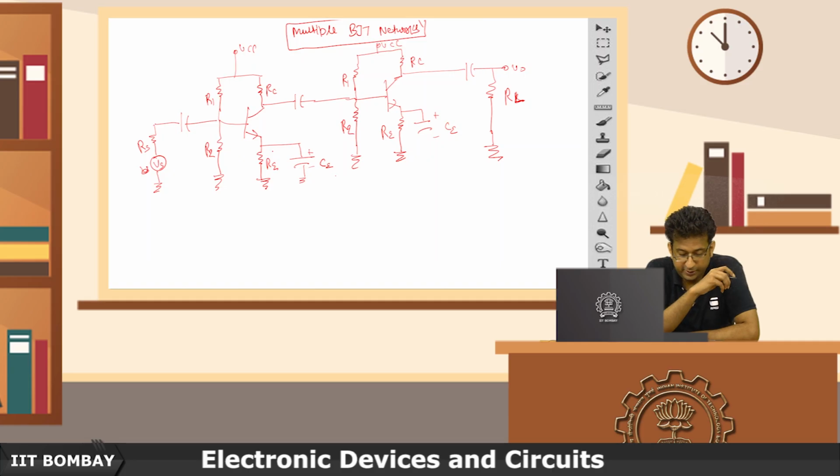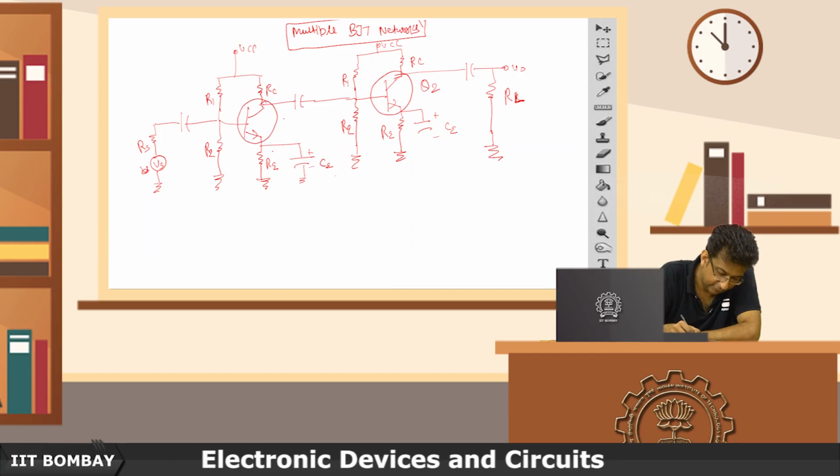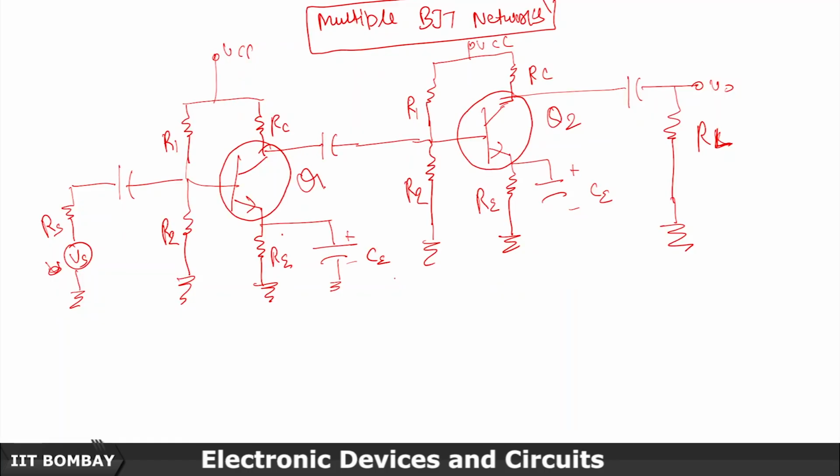So what do you see here? This is transistor 2, Q2, and this is transistor Q1. So the output of transistor 1 has been connected to transistor 2 through this load resistor at this point to largely constitute the base current basically, right, through these coupling capacitors.